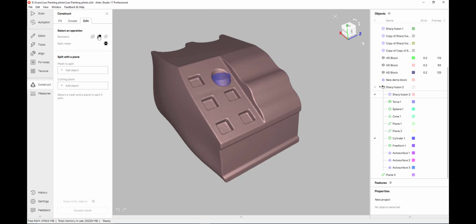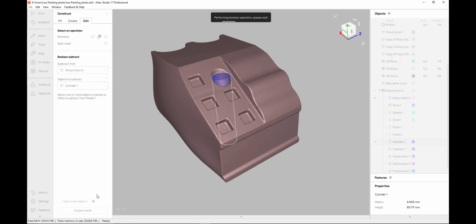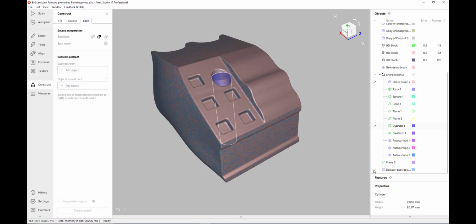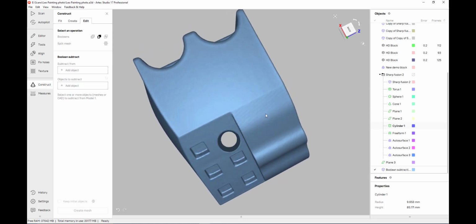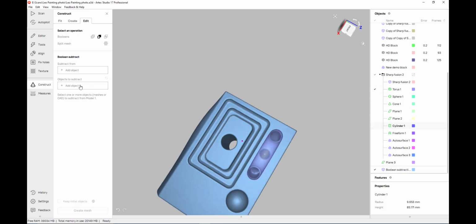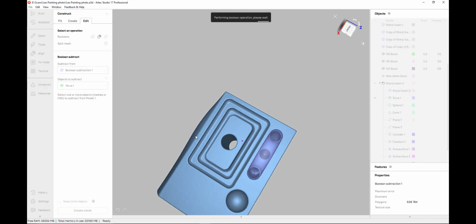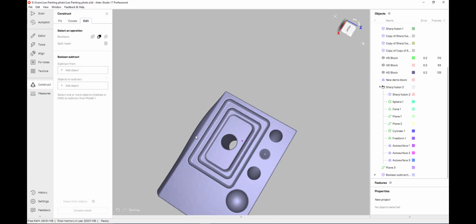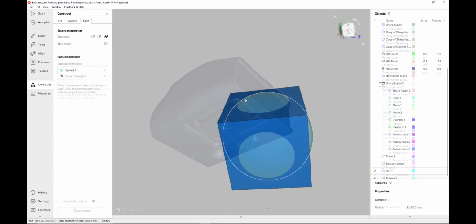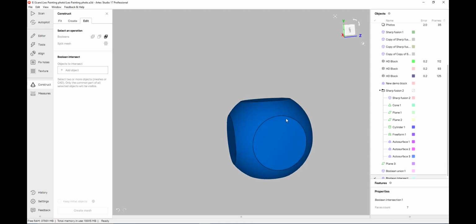Here, we're using an extracted cylinder to remove the filled-in mesh information from a hole we didn't fully scan. Once the Boolean finishes, we have a proper hole versus the partially filled one made during the meshing process. Being able to use the merge, split, and subtract tools, we can drastically change our mesh file in areas that didn't properly mesh, but need exact geometry or add information that may be handy for inspection and printing. The last edit tool is Intersect, which generates a new body based on where two features intersect.